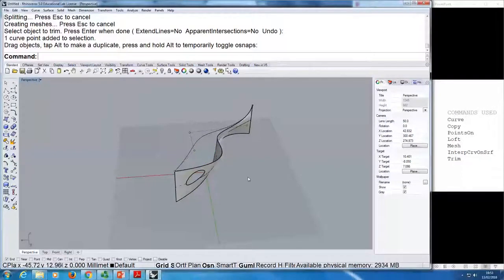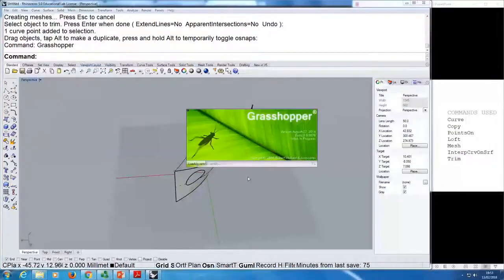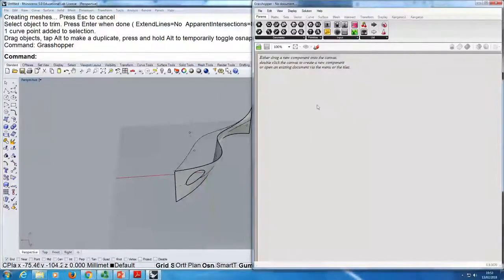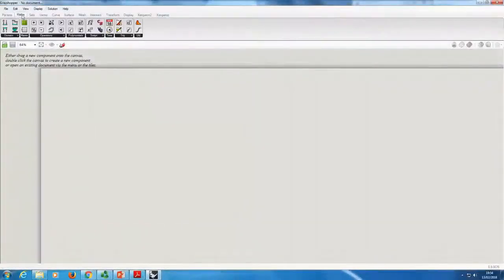And you might want to be able to do that when you do complex projects, and that's when Grasshopper comes into play. So if you open Grasshopper, I guess you don't need to for now, but if you type Grasshopper, you open it. Grasshopper is basically the explicit history of Rhino. So when you do steps, they will show. So quick intro to Grasshopper. You'll have a lot more in depth next week. But that's the canvas. Okay, I'll make it big for now. That's the canvas. You have components up here in different tabs.